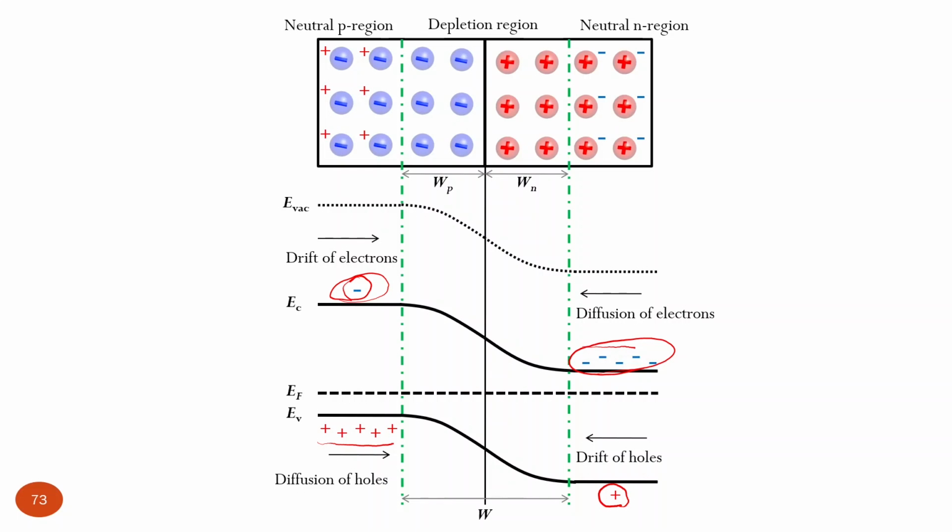So we were talking about the formation of the p-n junction. Initially, when we just put together two pieces of semiconductors, they start to diffuse, and this diffusion current is huge. But something happens. We build up space charges in the n and p-type semiconductors. These space charges are formed by immobilized ionized donors and acceptors, and they create an internal electric field. This internal electric field, which we have shown is linearly distributed, creates a quadratically distributed potential